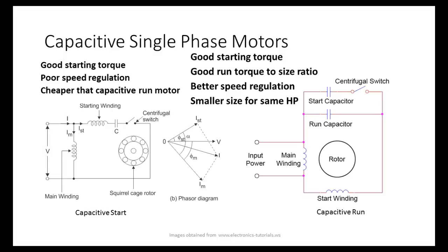Now we don't have that problem with a permanent magnet motor, because you only have 2 wires coming out of it. You don't have control of the field. So to change the direction of a DC motor, we leave the field alone and change the connection on the armature. That way, if you screw it up, the motor won't run. Right? You understand that?